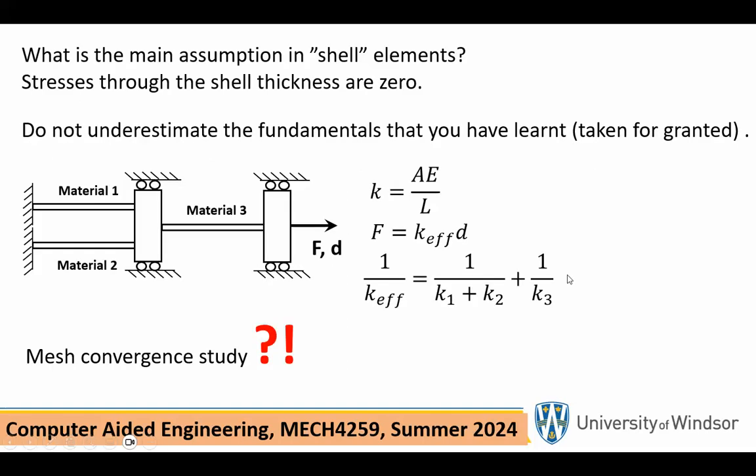All right. So first of all, let me quickly remind you about the concept of springs in parallel and springs in series. If you look at a situation like this, these rods, if these are two rods, for example, of different materials, you can approximate that rod with a spring of a stiffness AE over L, where A and E and L are associated with this top rod.